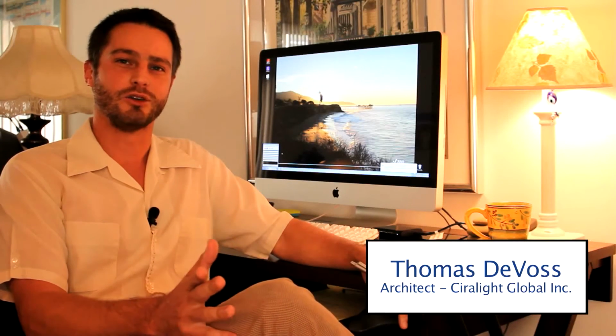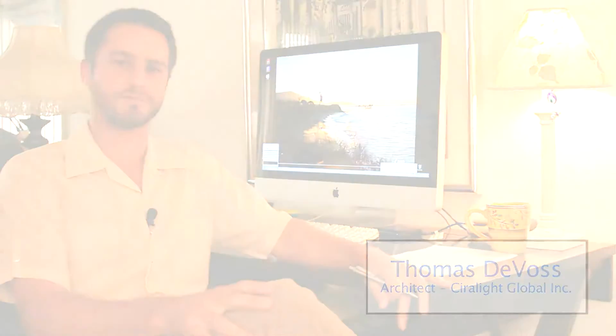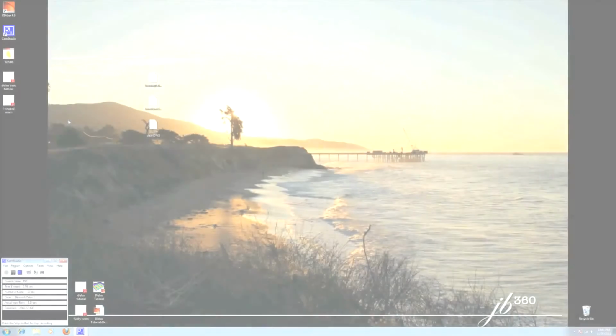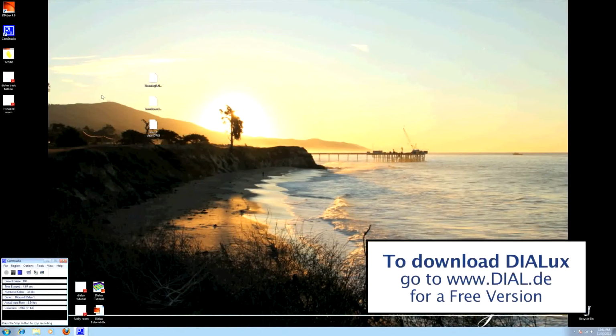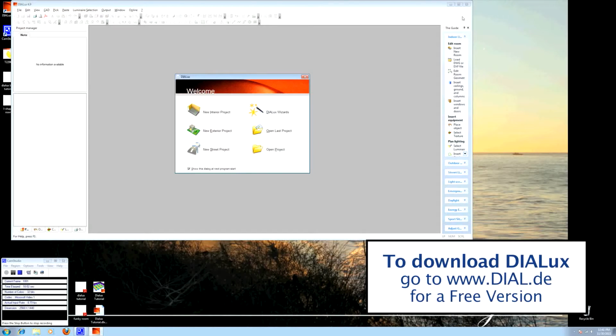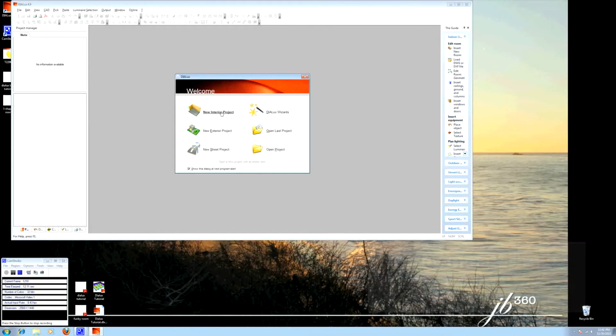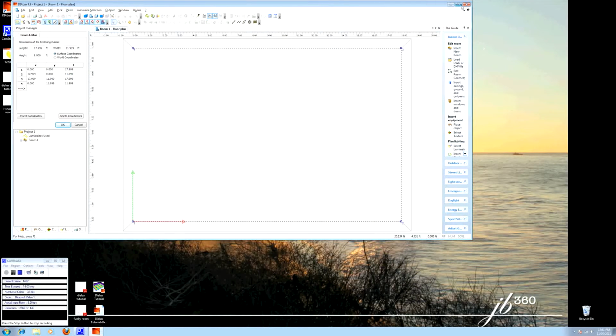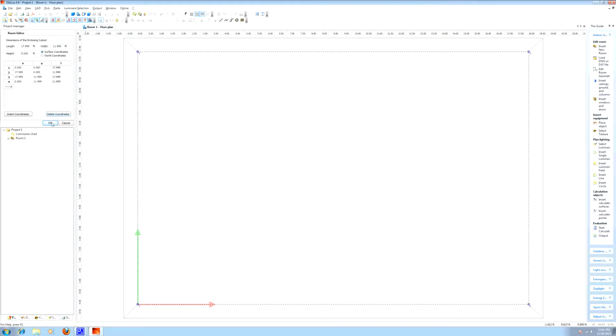I'm going to show you how to do a basic DIALux presentation. This presentation will show you how to create a DIALux presentation from an existing CAD drawing. So open up your DIALux. Let's click New Interior Project. Just click OK and we'll edit the room geometry later once we have our CAD imported.